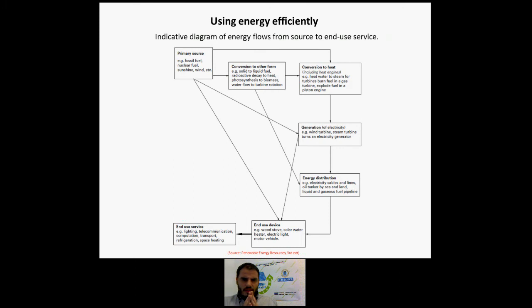The thermodynamic limitations of thermal conversion by heat engines are particularly important, as with vehicle combustion engines and with power station turbines for electricity generation. Carnot theory explains that only a fraction of input heat energy can be transformed into mechanical work output, with the remainder emitted to the environment as lower temperature heat. The practical consequence is that whatever heat is converted to work, as in engines and turbines, the mechanical efficiency is at best about 45%.